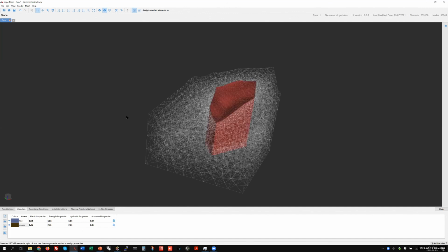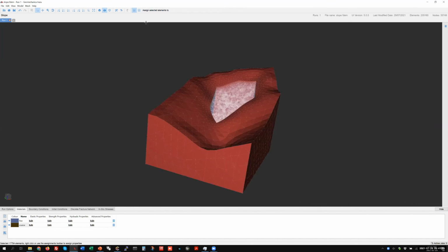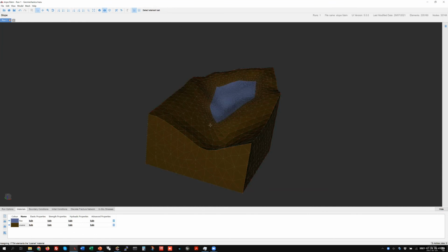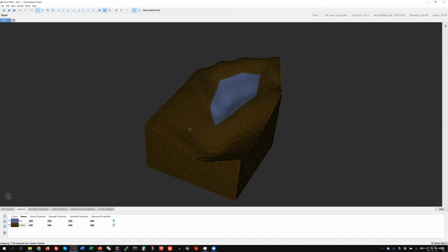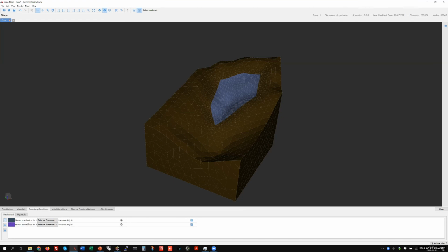So this is the fine volume. So you apply it to fine, and then you select the coarse, which is element block 2. You could also do it from the top here and apply to coarse. So as you noticed, it's so much easier when you group everything during meshing. Then you could go ahead and create your boundary conditions, the mechanical boundary conditions. So in this case, we need rollers on the sides and pins at the bottom.